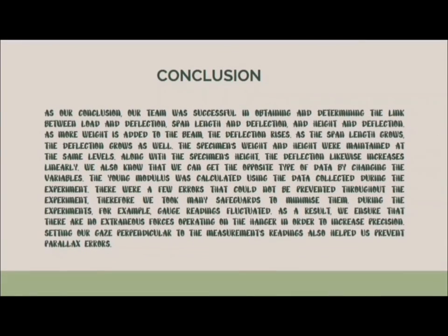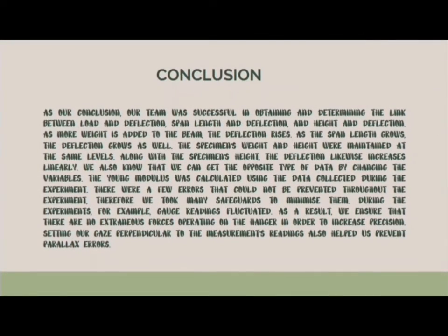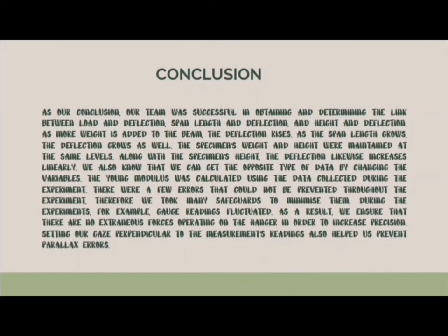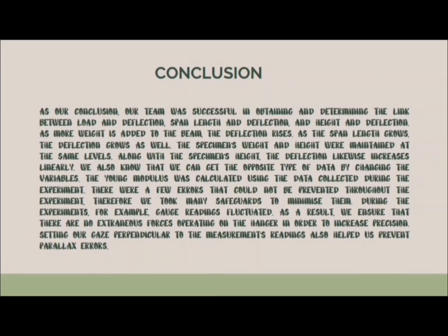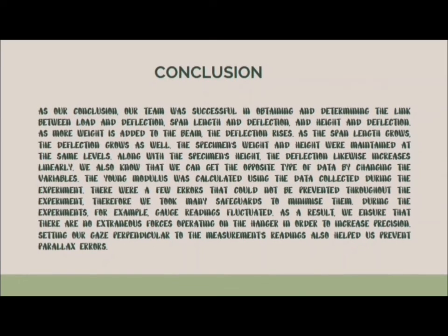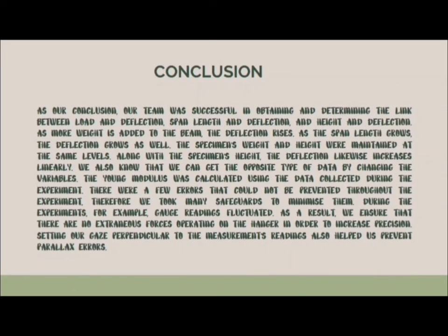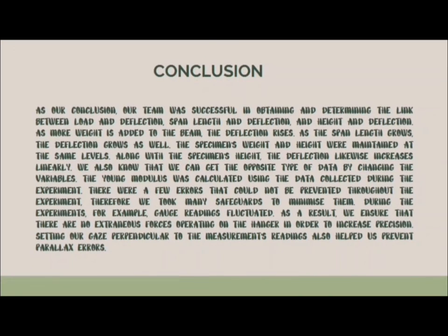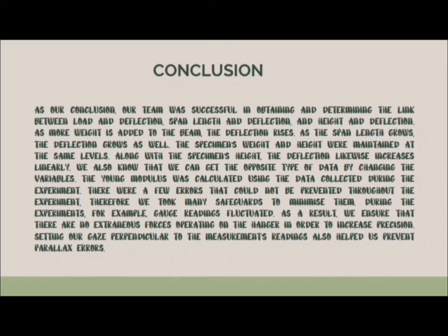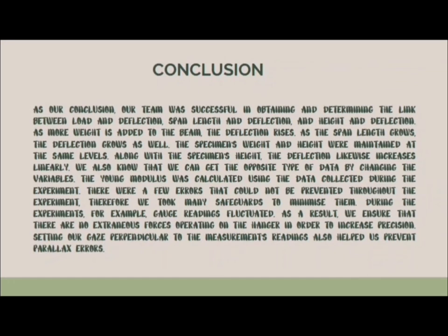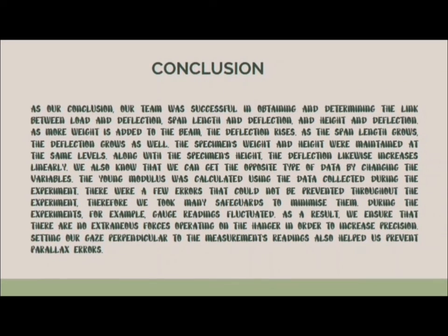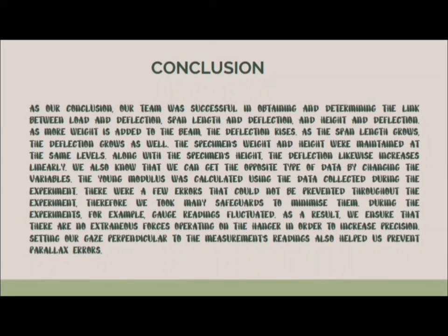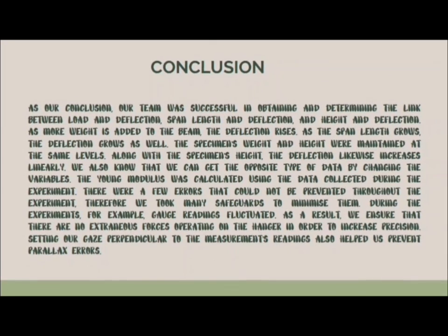Conclusion. As our conclusion, our team was successful in obtaining and determining the link between load and deflection, span length and deflection, and height and deflection. As more weight is added to the beam, the deflection rises. As the span length grows, the deflection grows as well. The specimen's weight and height were maintained at the same levels. Along with the specimen height, the deflection likewise increases linearly. We also know that we can get the opposite type of data by changing the variables.